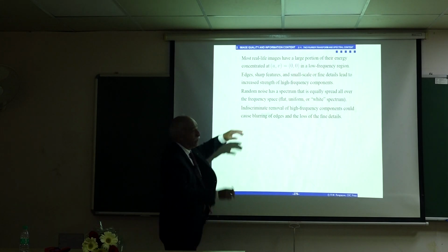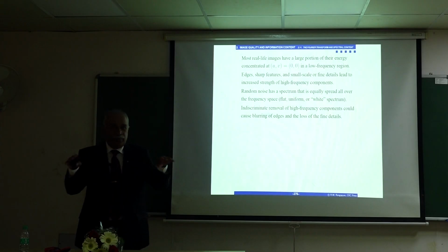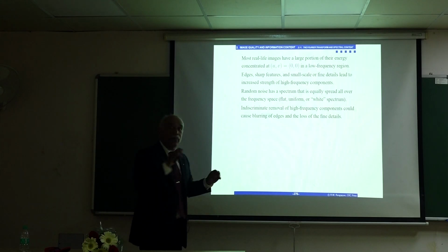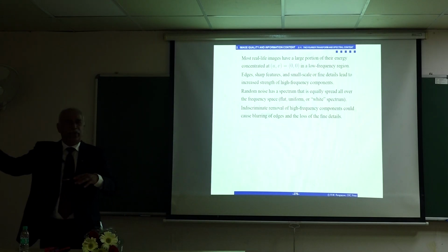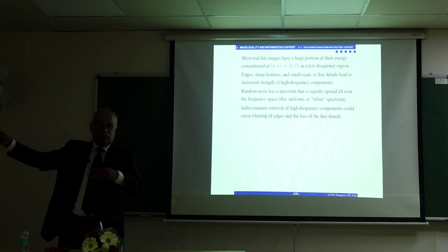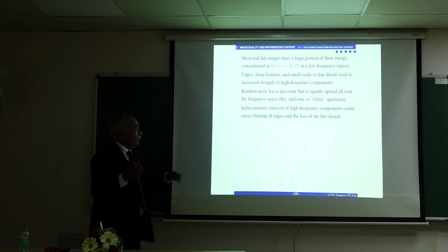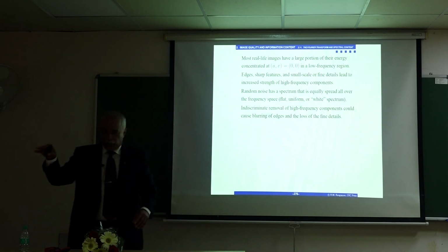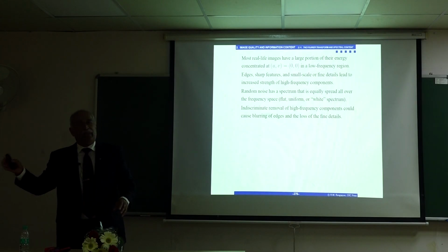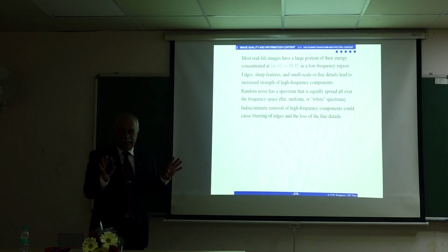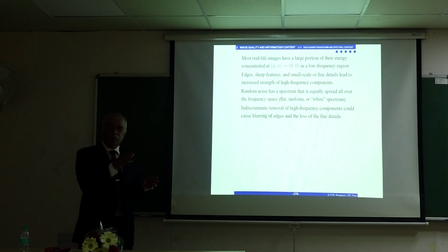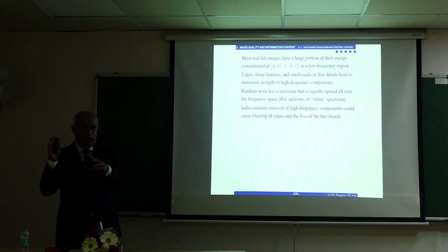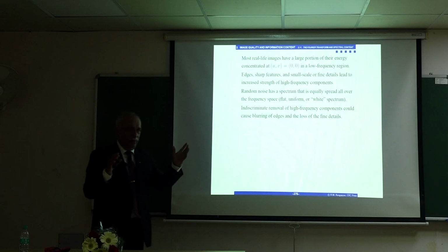But random noise has a spectrum that is flat, white noise, because the values are uncorrelated. So one may say, well, if high frequency is only noise, I'll cut that, use a low-pass filter, and remove all the high-frequency components. But in image processing with real-life images, there is some energy there. Although it is low, if you remove high-frequency components indiscriminately, your picture will be blurred. You remove noise, yes, but you also lose sharpness. So image sharpness translates to high-frequency energy in the frequency domain using the Fourier transform.